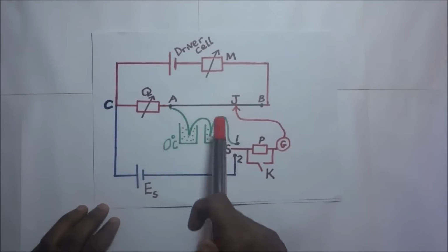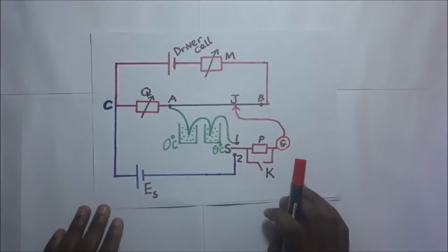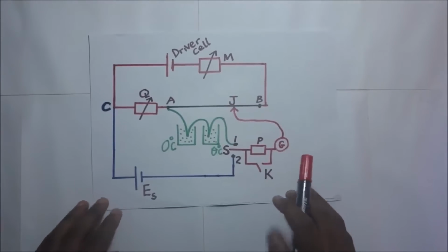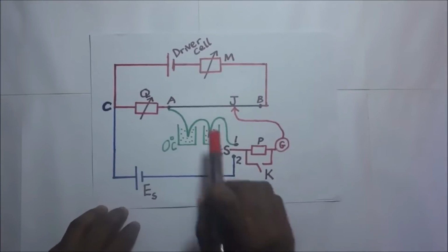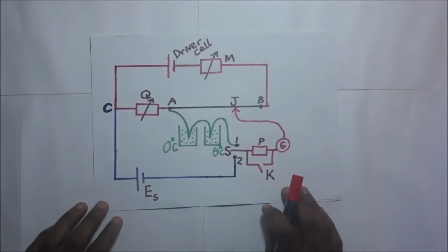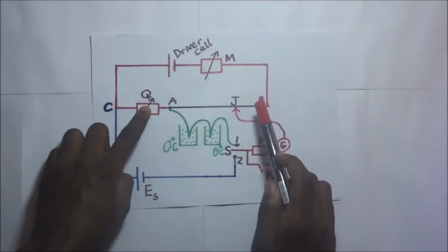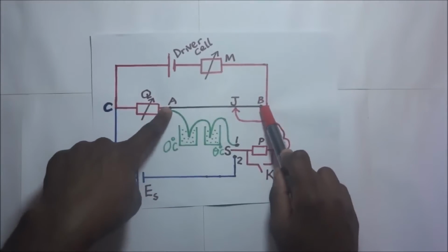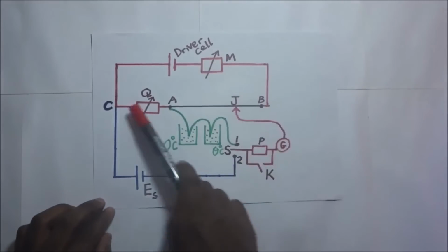Why should it be equally small? So that it's able to match up with this small thermometric EMF that we seek to find. We are able to achieve this by connecting a uniform slide wire in series with very high variable resistances, and these very high variable resistances are meant to minimize the amount of current flowing through.